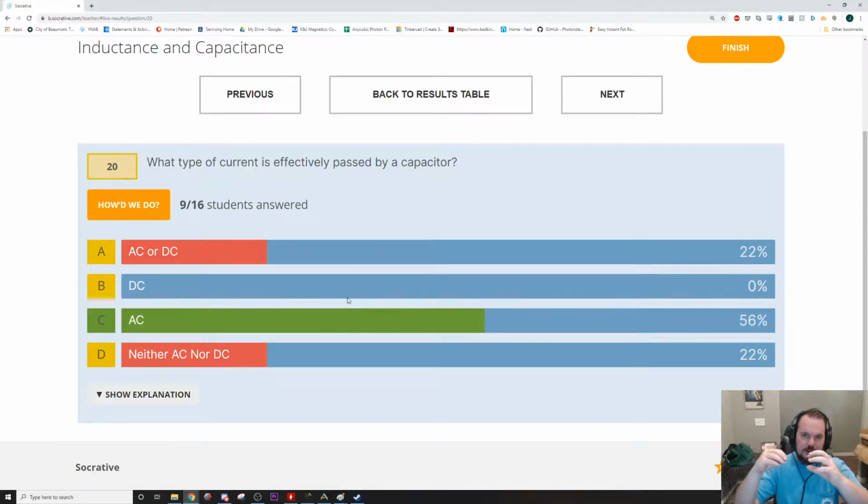As you start filling from one side, it inflates and pushes, and whenever it gets full, it stops the current flow. Then when you start discharging it, current flow starts again until it fills up the other side, and then it stops. With AC, the direction of current flow is constantly changing, so it's constantly charging and discharging, and it doesn't ever hit that maximum charge.